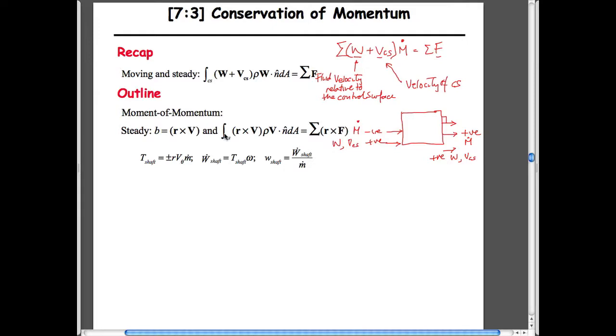So remember the sign conventions for this. Remember this kind of interesting issue here that the mass flow rate doesn't matter. The velocity of this cylinder, if we release it, is the velocity of the gas coming out of it. That's the equilibrium velocity if there are no forces acting against it. Of course, there would be friction on the floor. If it was airborne, for instance, there would also be air drag around it, but we're not worrying about that. And so it works out to be a very simple component.